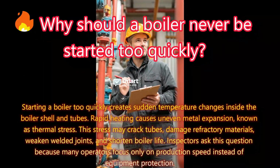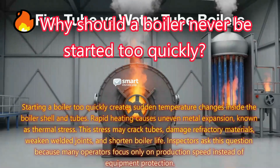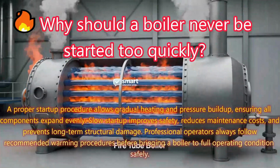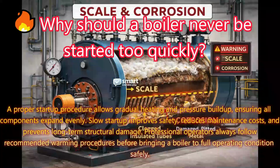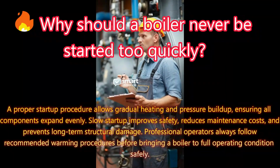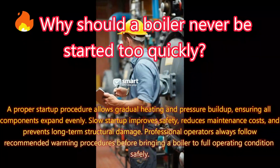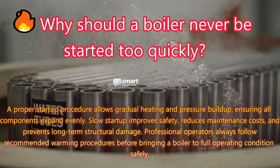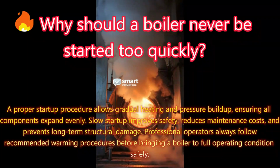Inspectors ask this question because many operators focus only on production speed instead of equipment protection. A proper startup procedure allows gradual heating and pressure buildup, ensuring all components expand evenly. Slow startup improves safety, reduces maintenance costs, and prevents long-term structural damage. Professional operators always follow recommended warming procedures before bringing a boiler to full operating condition safely.